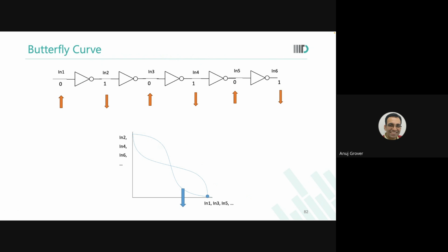So how much noise is okay? Let's reduce this noise a little. And you will realize that the noise that I will finally be able to handle is such that that is the maximum square that I can put in that particular lobe. And SNM being a min quantity, the minimum noise that can corrupt, I look at the smaller lobe. Whichever lobe is smaller, the biggest square that I can fit into it, the side of that square is my static noise margin.